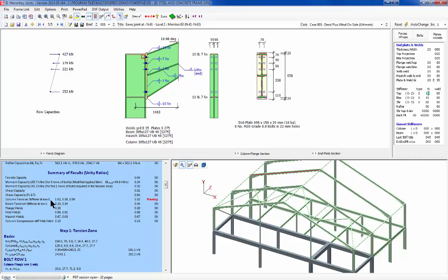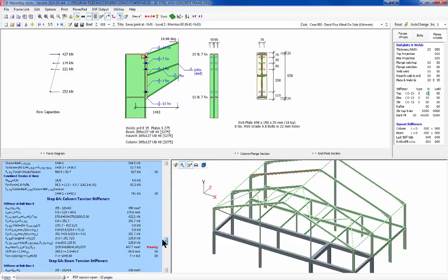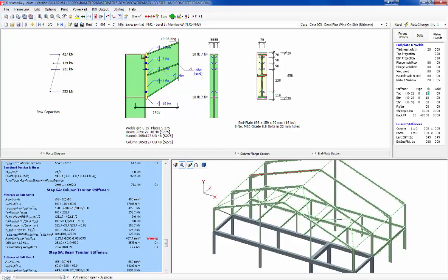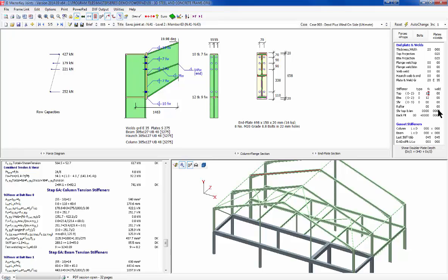Column tension stiffener and bolt row 0. I don't believe that's actually a problem. Column tension stiffeners. I don't believe there is a... Oh, this is in reversal. Yes, that's what it is. It's in reversal. So I wasn't reading, I wasn't thinking, and it's actually this needs to be a bigger stiffener. That's what the problem is, to work and close that down. So you don't need that, but I actually think sometimes a capping plate is a good thing. Keeps it nice and tight and conventional.